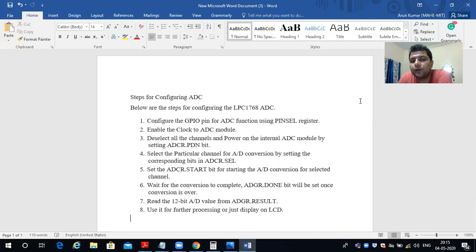For that we will use both ADC channel 4 and ADC channel 5 and give inputs to both channels, and whatever the output difference in the channels, the absolute output difference in terms of the digital value, we will display over the LCD screen. So one program is on the software controlled mode and another program will be on burst control.